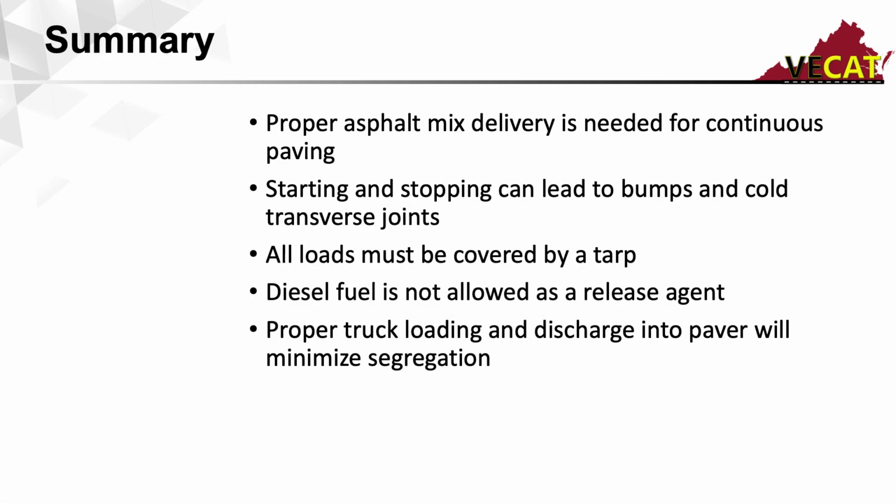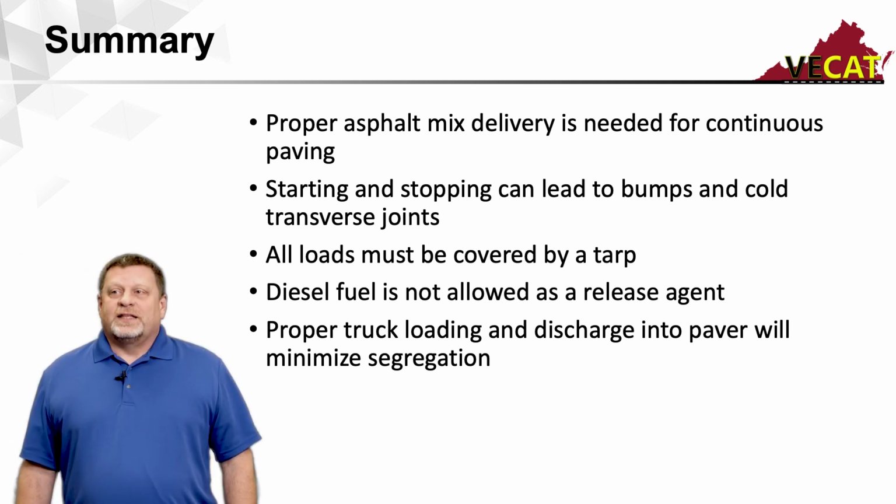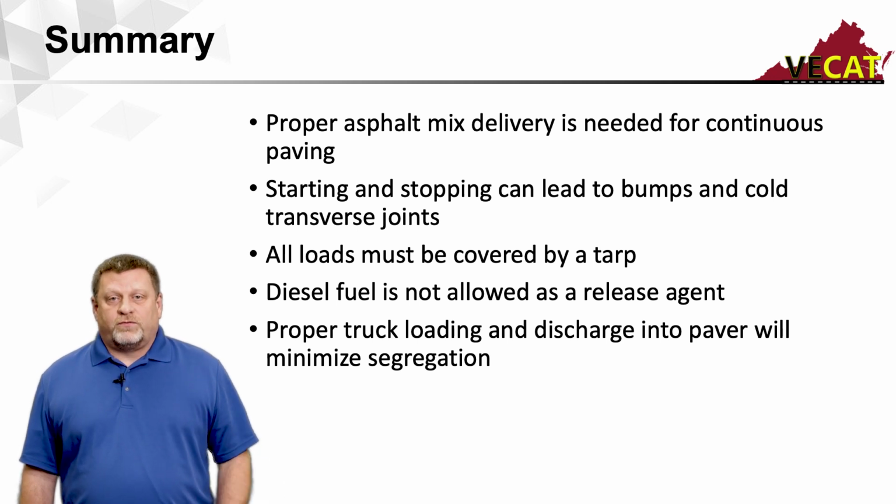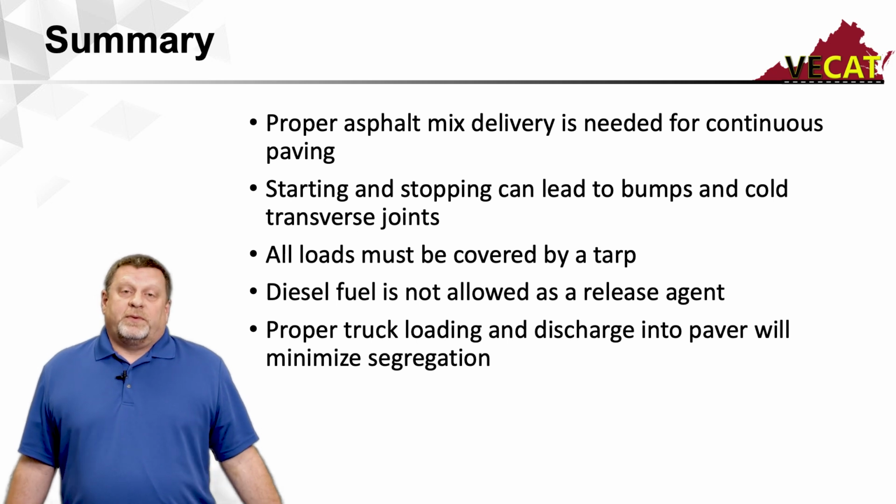And in summary, proper asphalt delivery is needed for a continuous paving operation. When a paving operation starts, the last thing you want to do is be stopping and starting in between each load. That creates a poor ride, poor uniformity of your mix, and it'll create bumps in the pavement. So it's important that during our mix delivery we keep a nice uniform flow of mix going into the paver. All our loads have to be tarped.